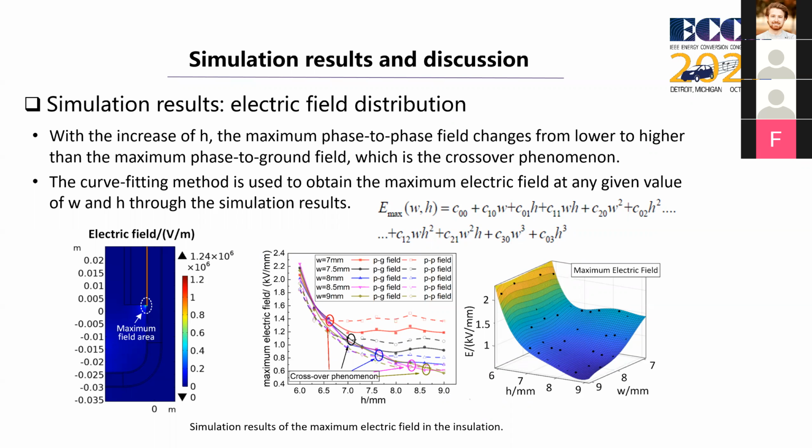The simulation results show the maximum electric field is located at the triple point in the end winding area, as shown in the bottom left figure, which is widely acknowledged. However, the maximum local electric field during the whole time will appear either at the moment of maximum phase-to-phase voltage or at the moment of line voltage, which corresponds to the position at a phase-to-ground insulation, or at the phase-to-phase insulation.